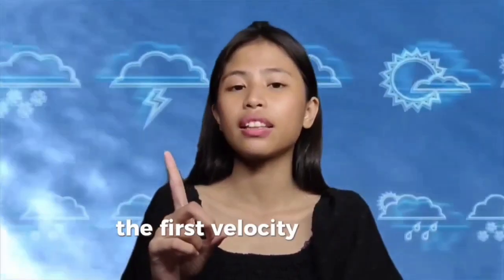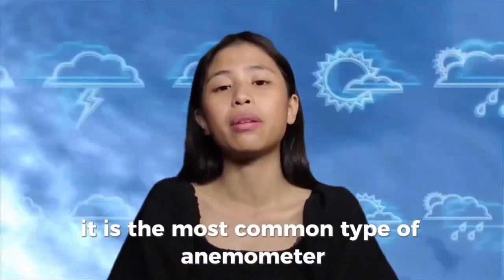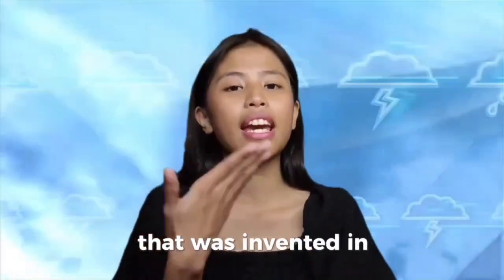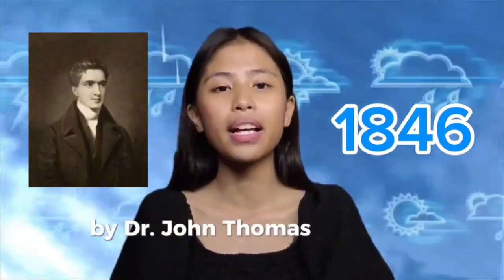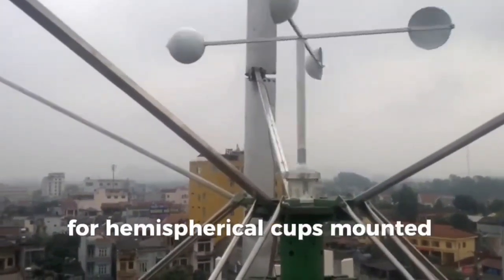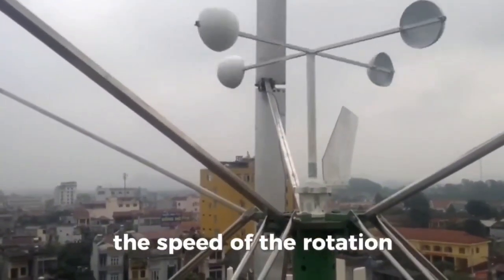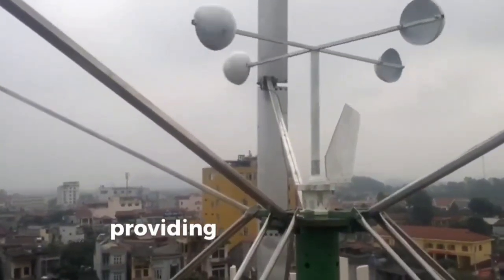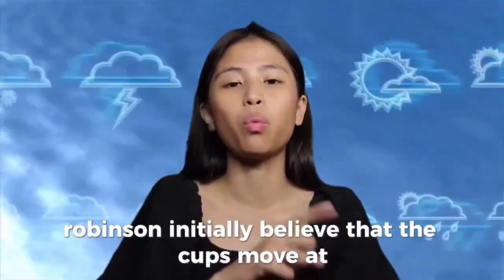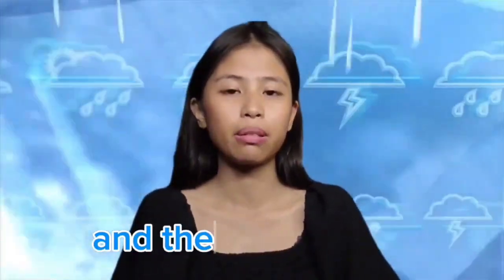The first velocity type of anemometer is the cup anemometer. It is the most common type of anemometer, invented in 1846 by Dr. John Thomas Romney Robinson. This design features four hemispherical cups mounted on horizontal arms which spin as the wind blows. The speed of the rotation is proportional to the wind speed, providing an easy way to measure it. Although Robinson initially believed that the cups move at 1/3 of the wind speed, further experiments revealed that the ratio varies based on the size of the cups and their placement.